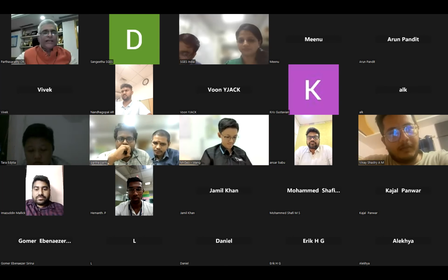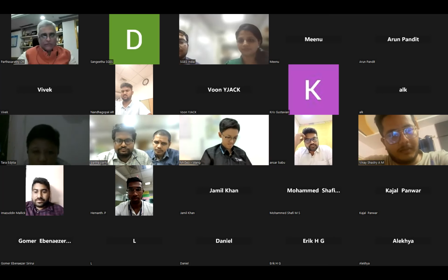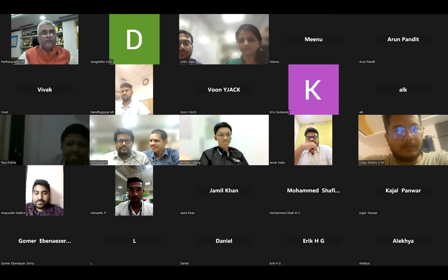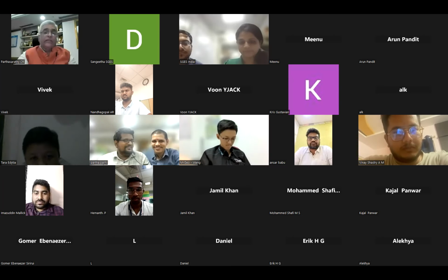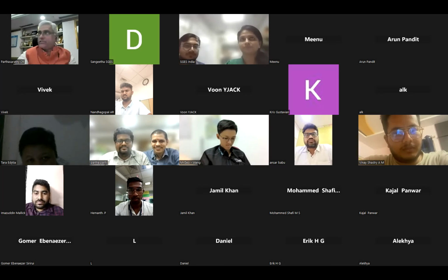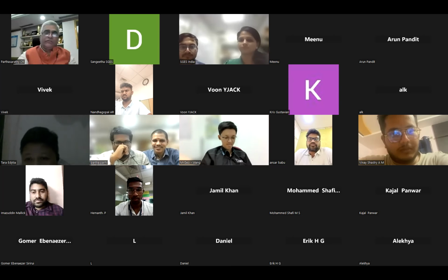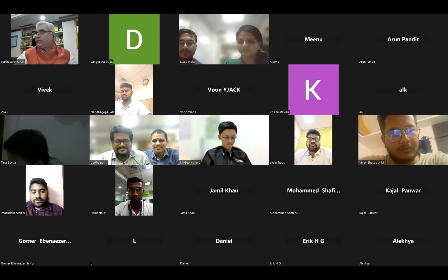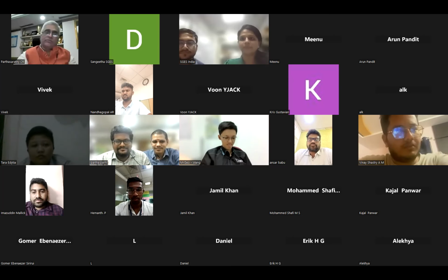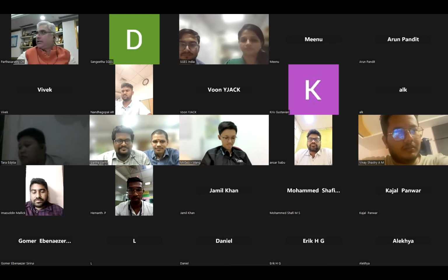So before accessing the CAPWAP, you need to assess the quality of the data. You need to have the data set start from zero. You need to have good proportionality. You need to have this force and velocity returning to zero. Then look at your individual sensors, the individual velocities: are they exactly on top of each other? If not, you can turn off one of them. You look at your strain sensors, maybe you have bending, severe bending, opposite bending.